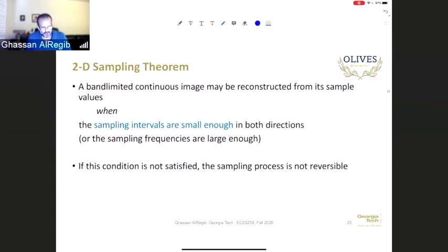In the interpolation discussion we will have next week, we cannot really implement the sinc function in the computer completely. So we have approximations: the zero order hold, bilinear, and bicubic functions that approximate the sinc function. We'll see about this next time we talk about interpolation. But for now, at least we have determined the conditions for when we can fully recover the signal if we are careful about the choices of capital X and capital Y.